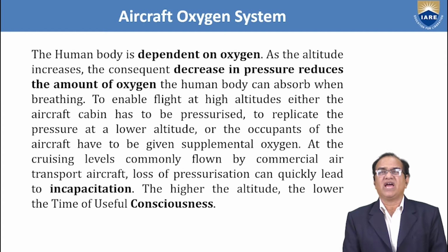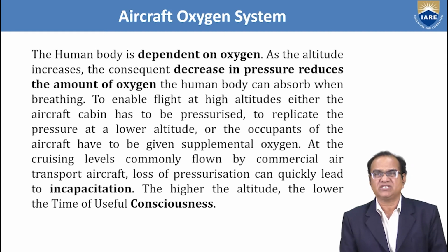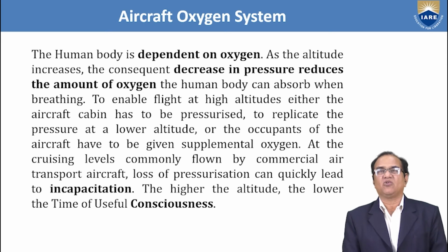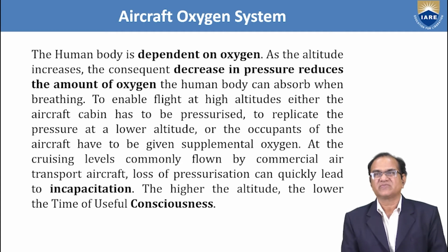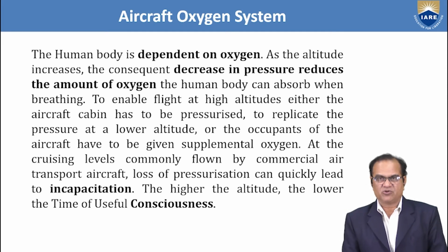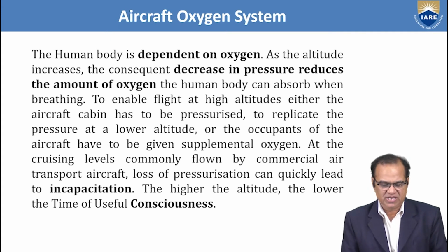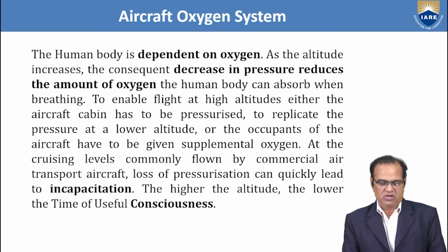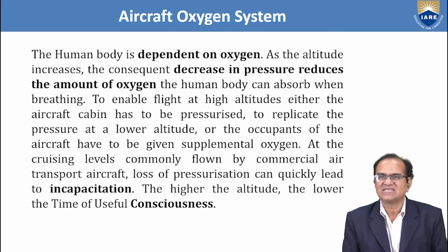To enable flight at high altitude, either the aircraft cabin has to be pressurized to replicate the pressure at a lower altitude, or the occupants of the aircraft have to supplement oxygen. At the cruising levels commonly flown by commercial air transport aircraft, loss of pressurization can quickly lead to incapacitation. The higher the altitude, the lower the time of useful consciousness.